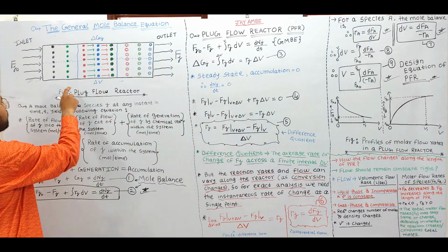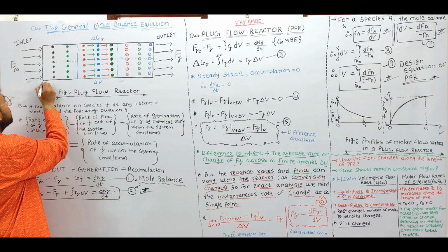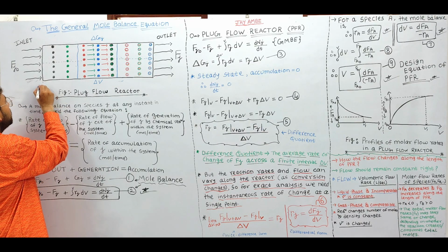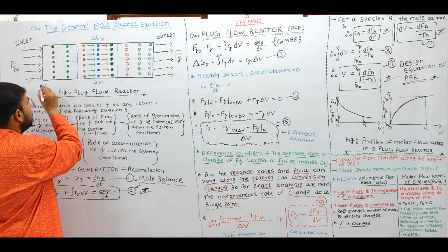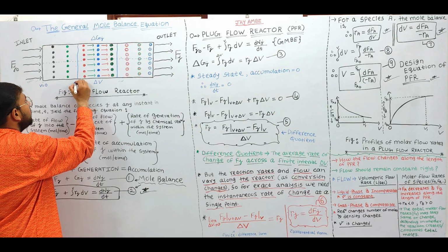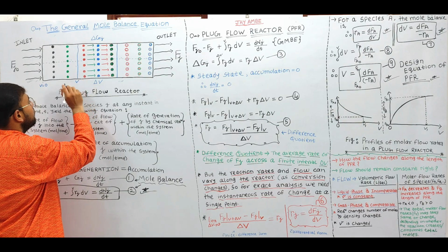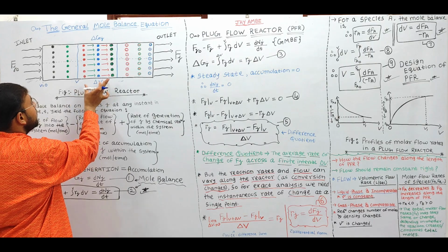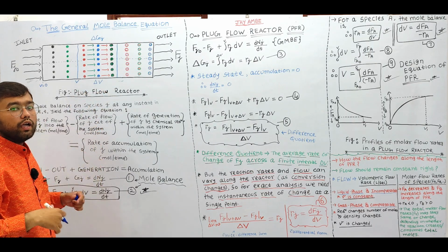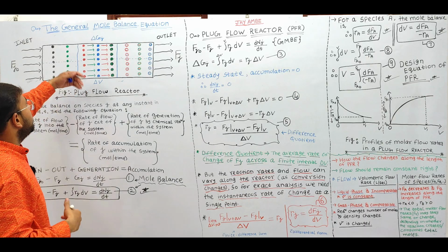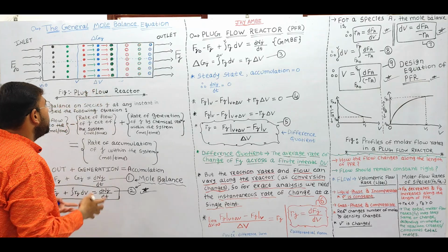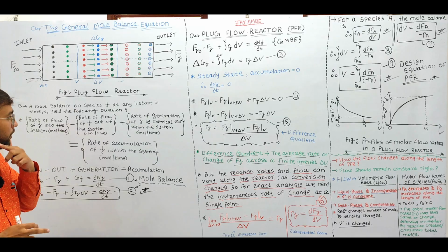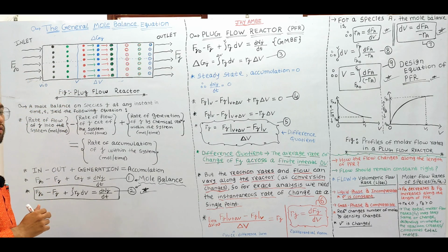So let's say here we will have the volume as V equal to 0, meaning the initial volume. And after here we'll have some certain volume, so from here to here we define a certain volume V. Because we are taking this finite volume into analysis, the part of our interest is the finite volume delta V. By understanding what is happening in the delta V, we will try to account for the entire reactor volume.